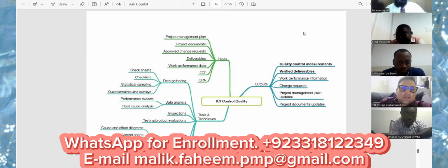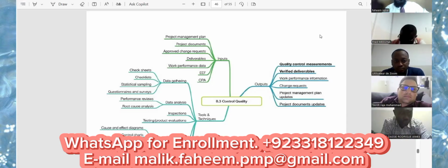Sir, I understand this like this: for example, we have 100 joints, but which are the critical joints? So we will sample out the critical joints and perform the inspection on that critical joint, and we will perform NDT on those ones. If it is okay, it means the rest of the 99 joints are okay. If we have a defect on that joint, then we will use 2 more joints.